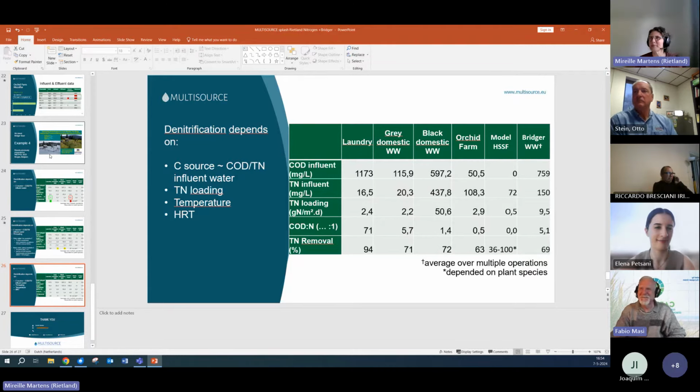We made a calculation, and actually from all the equipment present there, the pumps, the blowers, and the UV light, the UV is the most costly because it should be on 24/7. Because of that, the owner switched it off more than it was on, which should not be the case. But that's the thing that happens in real life. So that's why it didn't go ahead with the UV light. But anyway, the black water was never intended to be reused.